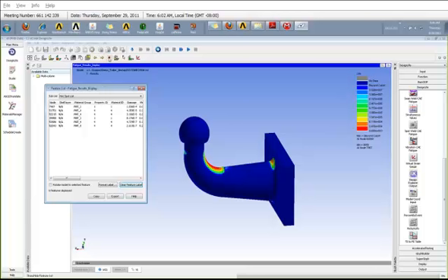So actually I can click on this button over here and look at those top localized damaged regions. So it lists my node numbers and the other material IDs. So let's go ahead and look at each one of them. I can click on this node over here, and it will show me where that node is in this contour plot. So that's where the neck radius is, and I can click here. That's my fillet radius, and that's on this elbow over here, and the other one is on my fillet down. In addition to this, it also gives me the damage, the non-proportionality, the maximum stress and minimum stress of these nodes, and the life of these.